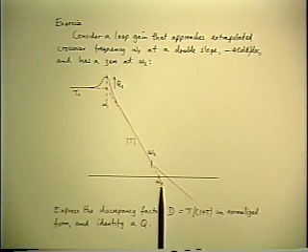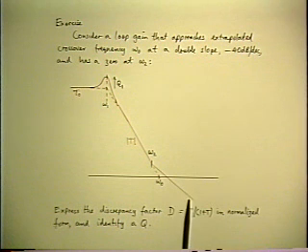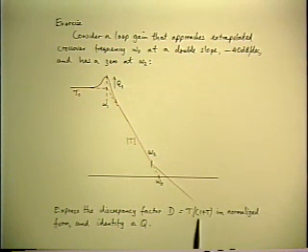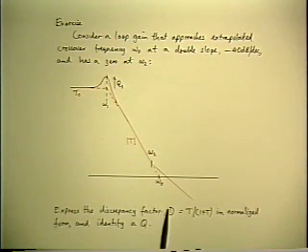This is an example not only of the hazards of putting a design out without even doing the analysis, but in this particular case it emphasizes the importance of the worst case, because they had also violated the other principle of design, which is don't make important parameters directly sensitive to uncontrolled parameters of your components.